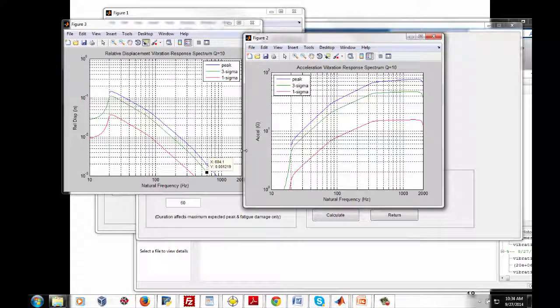So my solution is, okay, let's make the board itself as stiff as possible, and let's take that housing and mount it via compliant soft spring type grommets, bushings, or isolators. And that's really the ideal way of attenuating shock and vibration in order to ensure reliability and robust design and performance and longevity and all those good things.